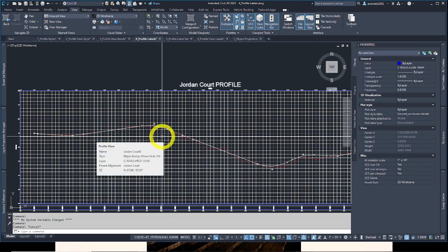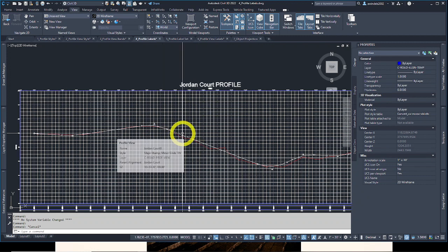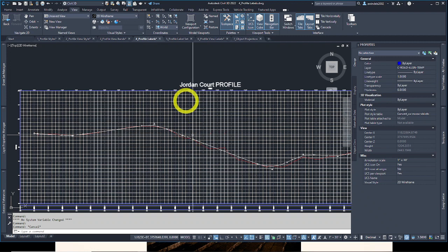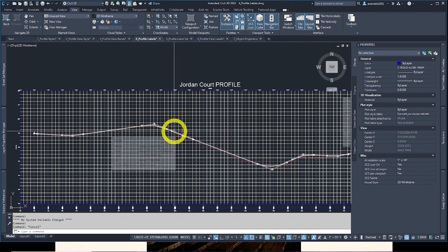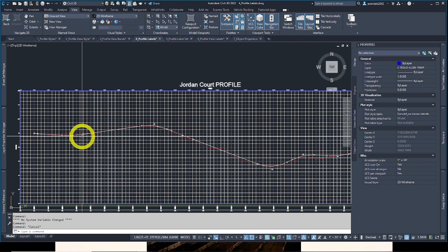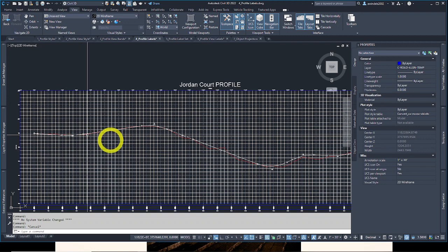Another advantage, these labels appear whenever new geometries are added. So once a whole label set's added, they act dynamically. If we're working on a really long stretch of highway or canal with a whole bunch of curves or whatever, it's nice when they repopulate automatically instead of having to delete them. When you add a vertical curve, let's add another one here, they will disappear and delete automatically at times too.